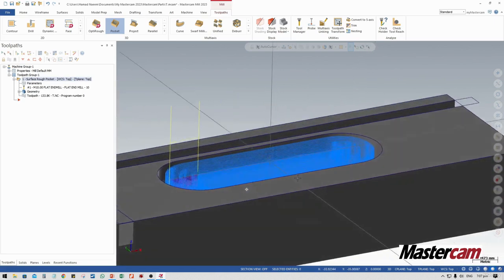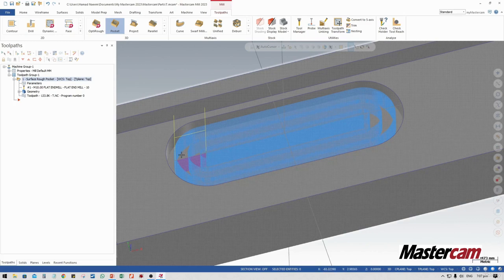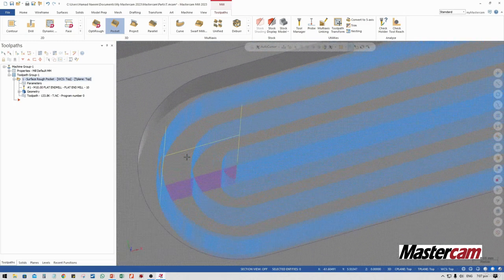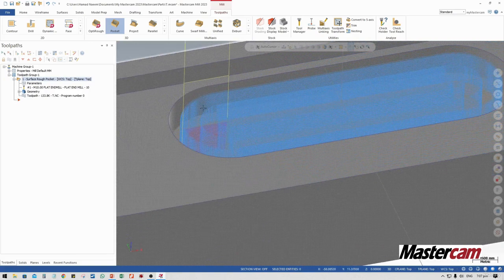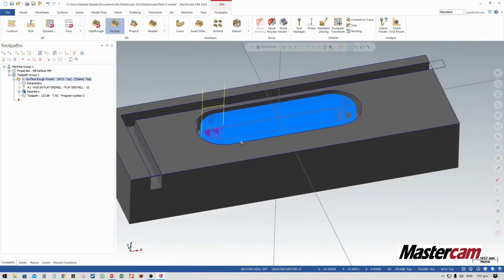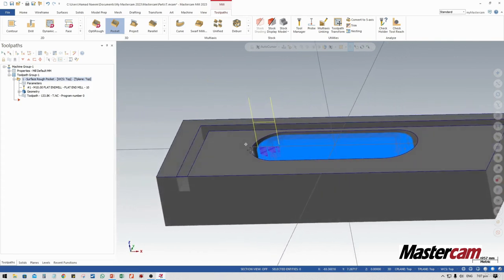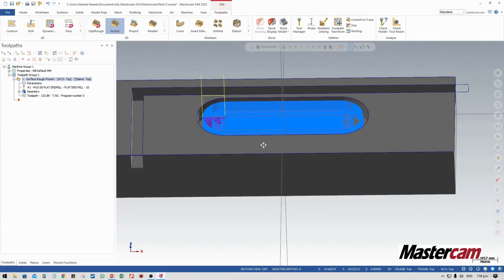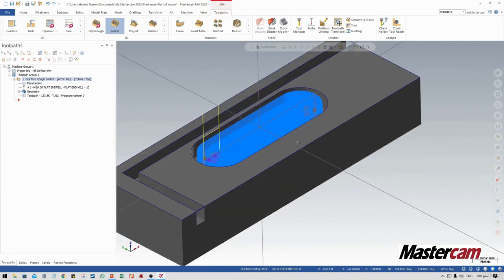So here you see that it creates a toolpath of the 3D model and makes a depth of 15 millimeter in this pocket. So we take 0.5 millimeter depth cuts, and it will go down from the top of the stock to minus 15 millimeter, and creates this pocket. So this is how we can create 3D toolpaths. Just to give you an idea how we are going to perform 3D toolpaths for our 3D models.